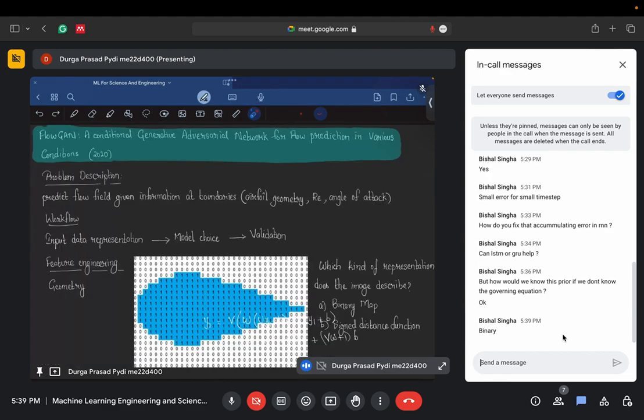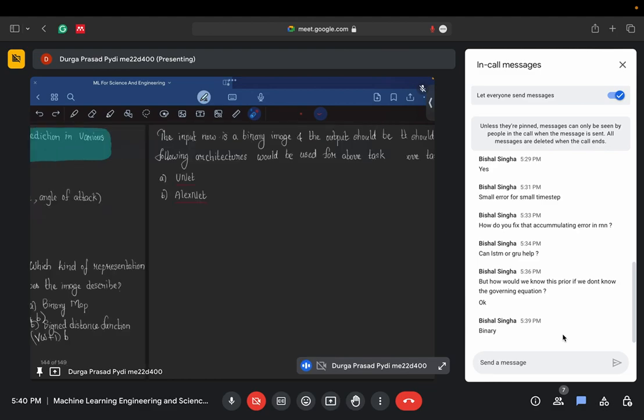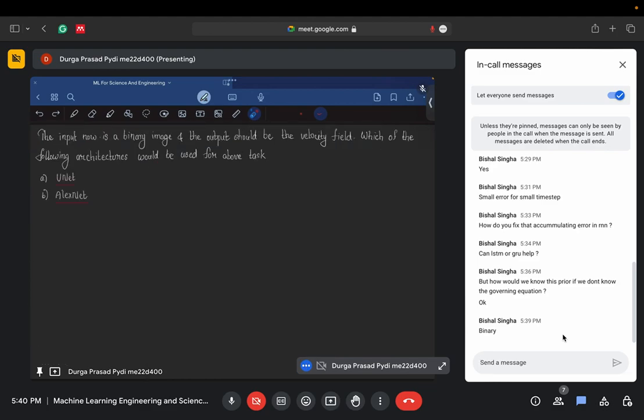What we are trying to do here is provide this particular geometry as input to my network, and the output that I want is the velocity field at every other point inside this domain. Basically, wherever there is a 0, I need to replace that 0 with the actual velocity field there. Let's say I'll have two images, one for u and one for v, basically one for the horizontal velocity component and one for the vertical velocity component, the x and y components. That is my objective. I have chosen to use a CNN for this purpose. Basically I have an input image, and I want to get the velocity fields as my output image. So my input is an image and the output is an image.